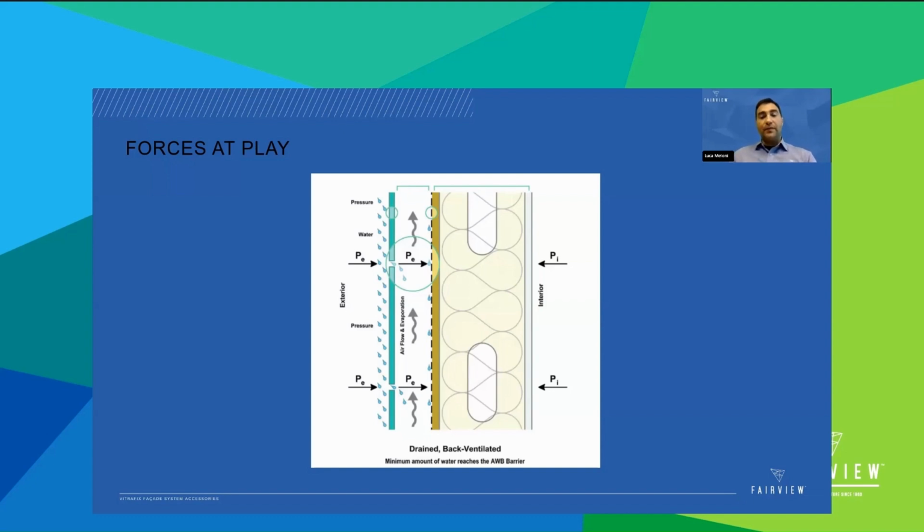It is critical to prevent water from seeping into building walls and slowly destroying the structures from within. Therefore, a moisture-resistant envelope is a top priority for buildings, regardless of their age or use. Holes, gaps, and cracks, joints around doors and windows, and porous exterior materials such as brick, stone, and concrete can allow harmful moisture into the building structure.